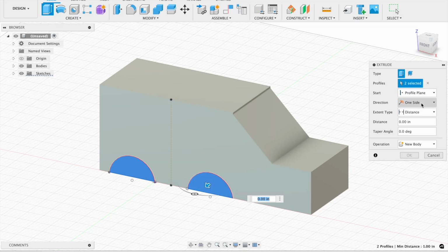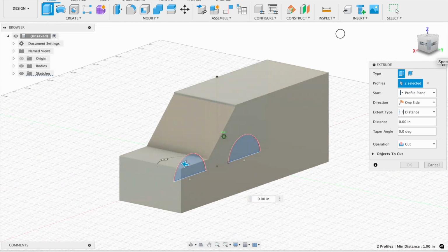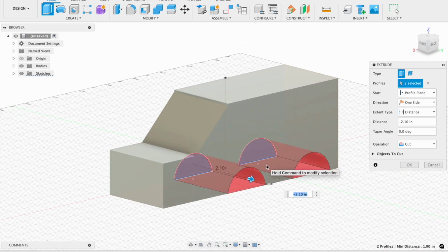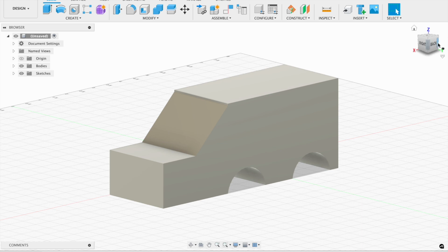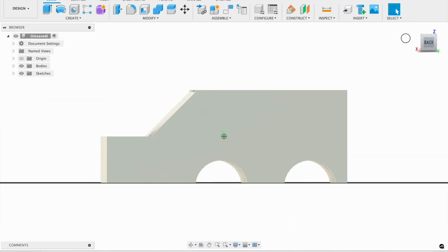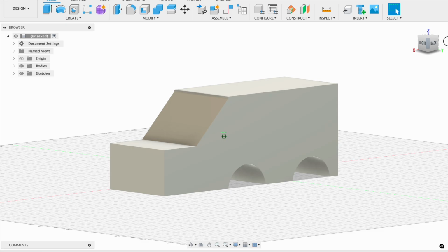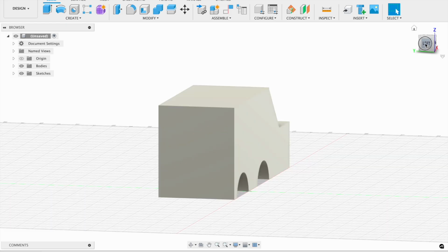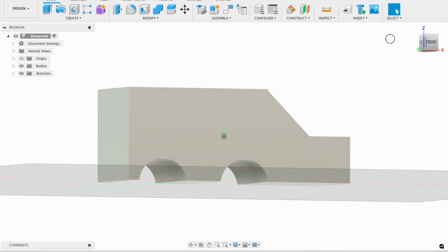So now we're going to see the cut function of extrude. Essentially, you click it or make it a negative number. That will have the closed geometry cut into the other shape. You can honestly have it go to the other side of that plane, like I did, and you just cut something out using extrude. It's really easy and it's really fun.